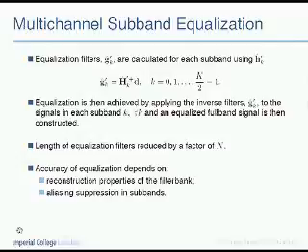And if you now have these estimates, you can design your equalizing filters for each subband based on these subband equivalent filters. And you achieve the overall equalization by applying the filters to each subband and then reconstructing the equalized full band signal. And of course, since the impulse responses of the room transfer functions have been reduced by a factor of N, the decimation, so do the equalizers.